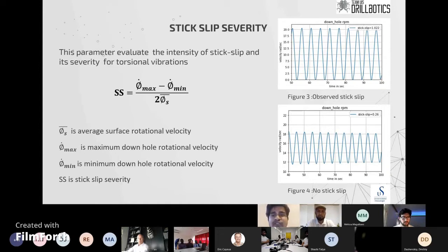Torsional vibrations occur due to frictional forces between the drill string and BHA. These vibrations can cause damage to drill string components during downhole operations. Understanding the cause and reducing torsional vibrations by implementing corrective actions helps in drilling optimization. This is the main focus of our study.